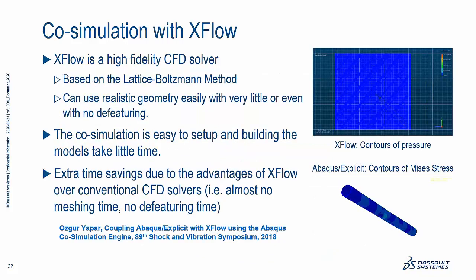And one of the more recent enhancements is our ability to co-simulate between Abaqus Explicit and our lattice-Boltzmann-based CFD solver known as XFlow, which is a relatively recent acquisition by Dassault Systèmes. One of the wonderful advantages of XFlow, in addition to it being a phenomenal CFD solver, is that for those of us who are familiar with structural mechanics, the setup of these problems is extremely easy.